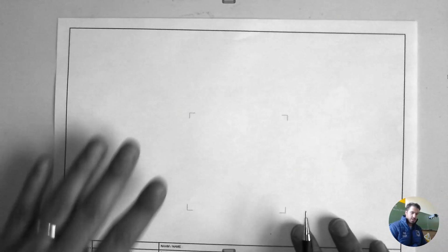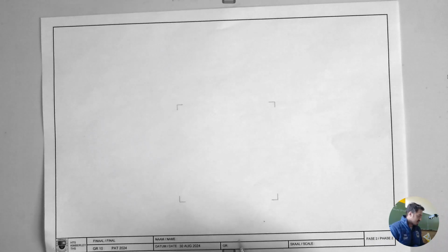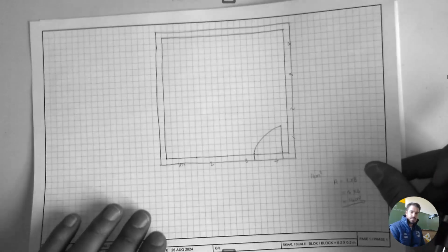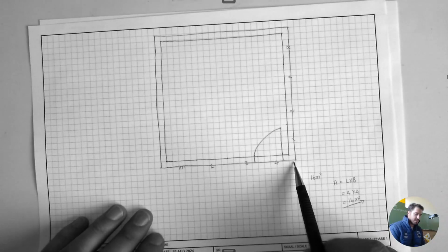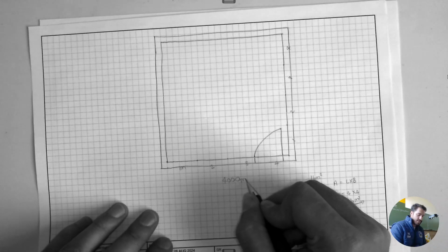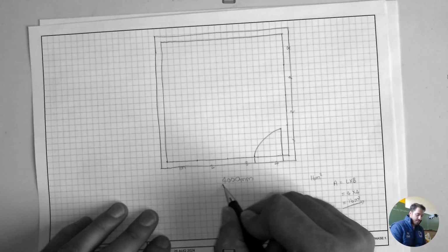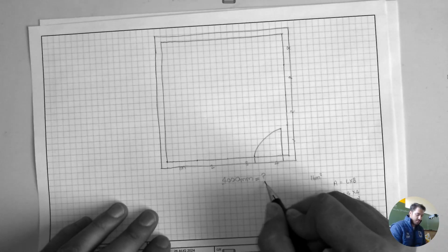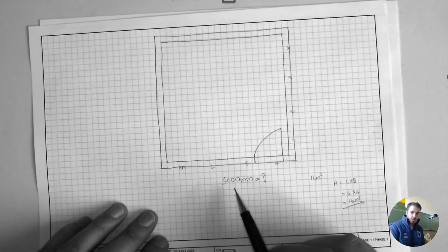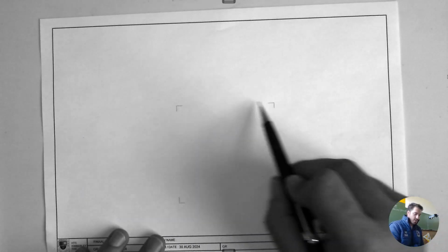This is where you have your final product or your final draft for your floor plan. You just have to take your floor plan that you've designed. Let's say this is the one I've chosen. And then if this is 4 meters, remember now, 4 meters equals 4,000 millimeters. If you divide this by 50, you get a specific amount. I don't want to give you the answer because you have to work this out. So you have to take this number and then divide it by 50. That's going to give you the lines that you have here.